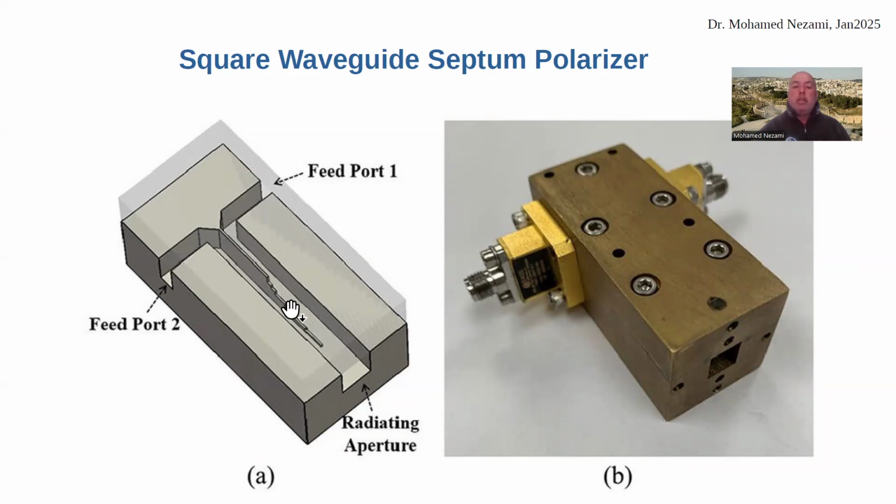You can see the assembly design goes from a square waveguide to two parallel rectangular waveguides. Of course, you can attach a coaxial to waveguide transition on there as well, so that you can get back to cable. This is done with CNC machined aluminum pieces.